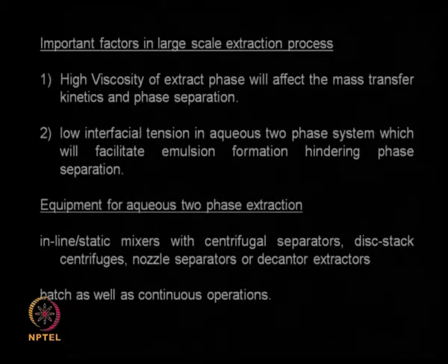Because of the high viscosity, there are going to be mass transfer limitations both during the extraction as well as in the phase separation, because after you do the extraction you are going to allow both the phases to separate, and because the phases are highly viscous, the separation is also going to take a very long time. Not only is the extraction mass transfer limited, the separation is also going to take a much longer time. That is one problem.